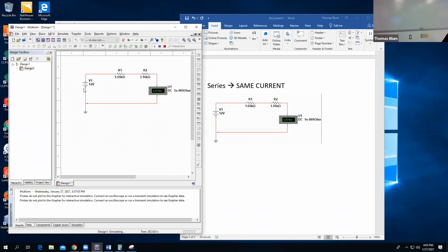incandescent lights are just a simple resistor. And you send some current through the resistor of an incandescent light bulb, an old-fashioned light bulb, and it gets hot enough. So it's giving off so much heat that the heat becomes visible. The toaster becomes a little bit visible, and then it sort of maybe becomes orange. The light bulb wire's not as thick, but what wire there is is hotter. And so then that light is a higher temperature, and therefore it becomes like white light.